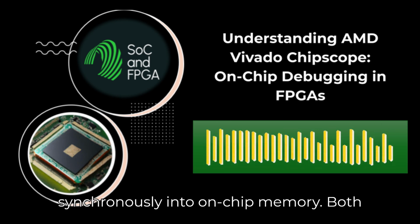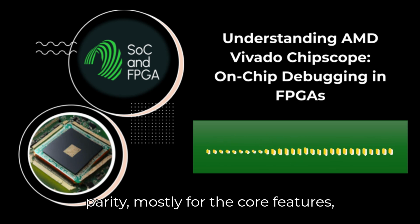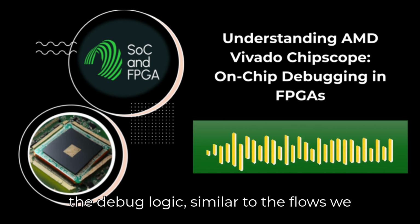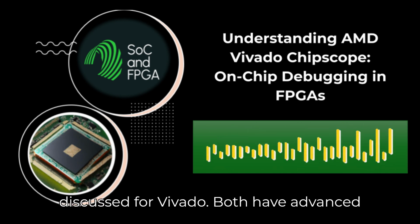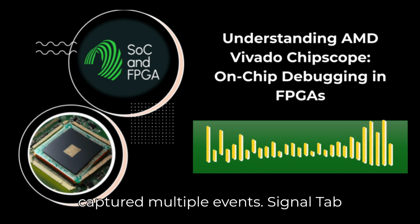Both capture data synchronously into on-chip memory. Both have configurable triggers. So feature parity, mostly. For the core features, yes. Both offer multiple ways to insert the debug logic, similar to the flows we discussed for Vivado. Both have advanced features like segmented buffers for capturing multiple events.